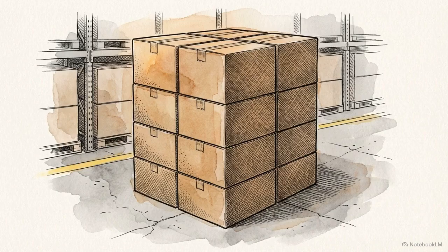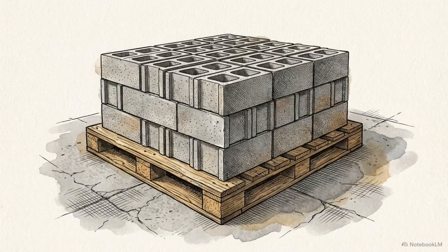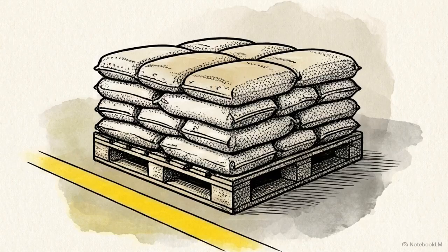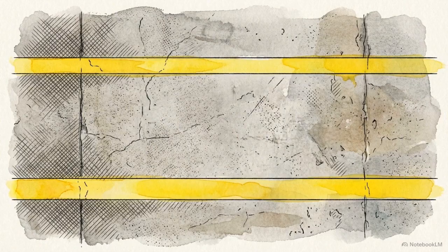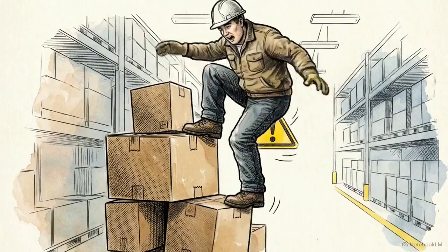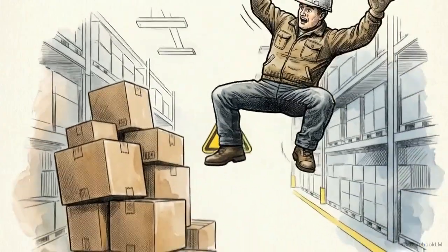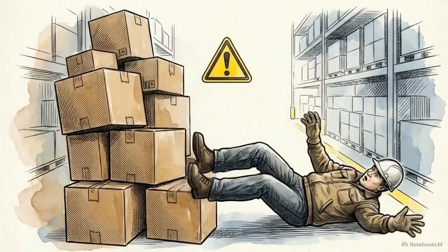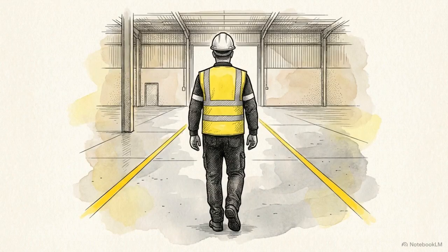Safe material storage follows strict rules. Pallets must bear cumulative loads. Bag ends must face inwards, and walkways require clear demarcation. You must never climb stacks of materials. The safety regulations mandate using ladders, making free climbing an absolute prohibition. Implementing proper housekeeping eliminates the trip and collapse hazards that cause the majority of workplace injuries.